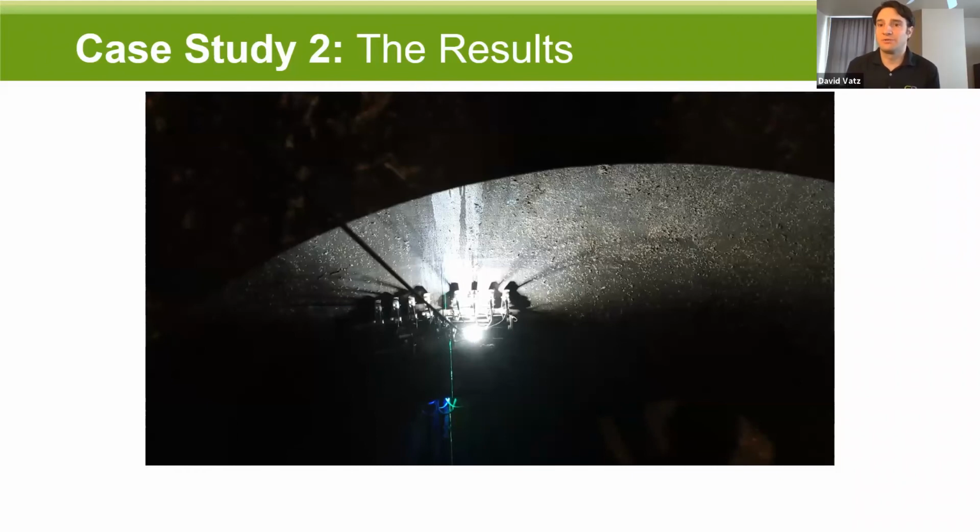Sorry, can you repeat the question? Yes, in a pipe, how does the robot handle deposits? For our robot right now, we're only doing scans from the outside diameter of a pipe. We would handle deposits the same way we would on a boiler tube: we evaluate the UT signal with a combination of computer algorithms and human evaluation to understand whether what we're seeing is indicative of a bad signal versus under deposit corrosion or some sort of underside deposit.